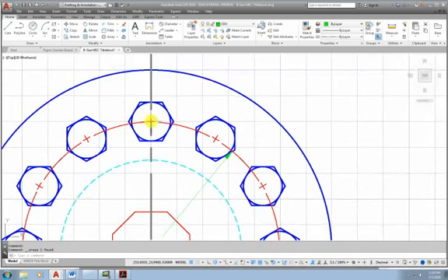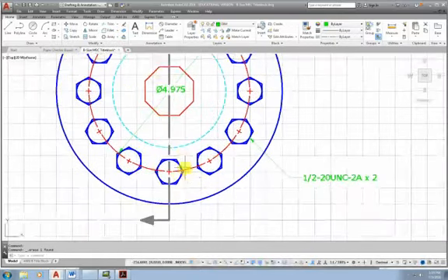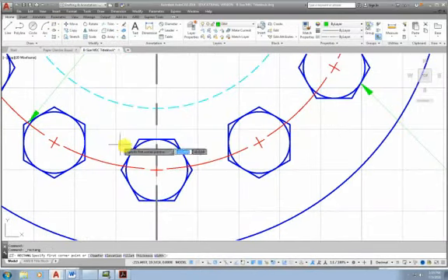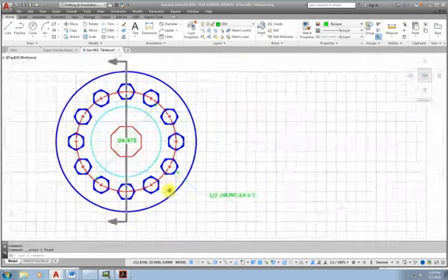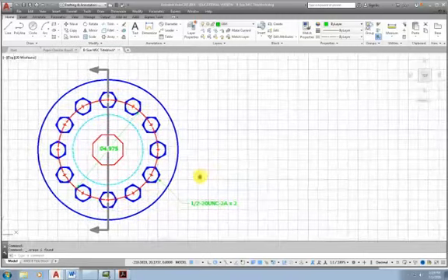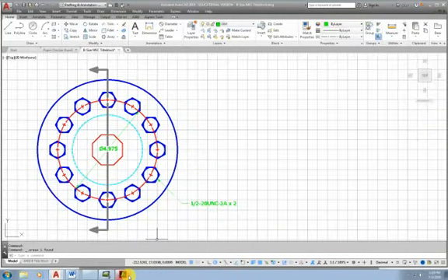And again, this area too, I'm going to clean that up, so I'll draw a little square here, and then I'll say trim, click on that, hit enter, and I'll trim that out, and then I'll get rid of that, and I'll do the same here. Now that's not to say that every drawing has to have this level of detail. I'm just showing tips and tricks as we go through and work on this. Is there going to be a big problem if I didn't do this when they manufacture? No, not really.